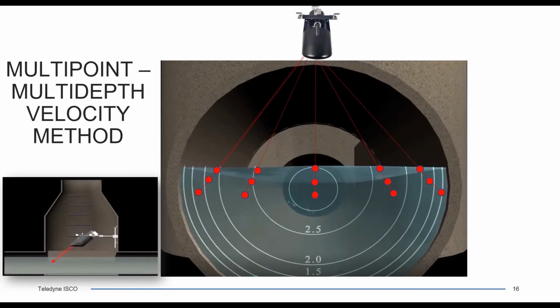If I have a pump station application where my flow is rapidly changing, maybe this isn't the best thing for you. You may only want a couple points. If I have batteries, I may not want to run all these. If my flow is uniform and all the readings are close to the same, then you may not need it. It doesn't hurt anything to have them on, but you will sacrifice a little bit in time to get the reading as well as power.